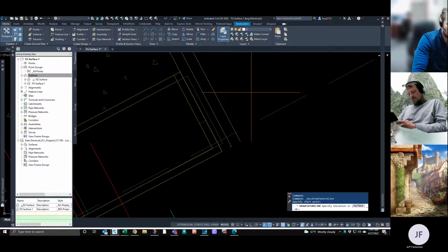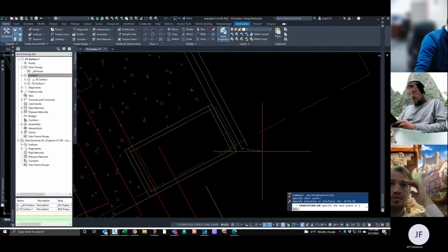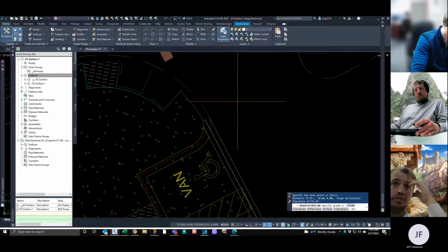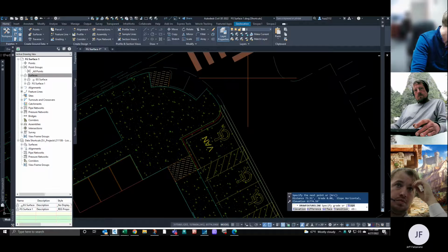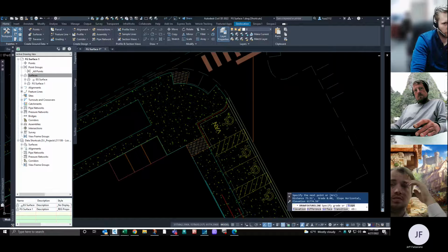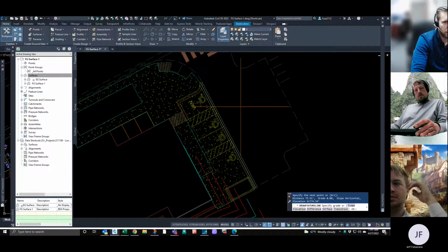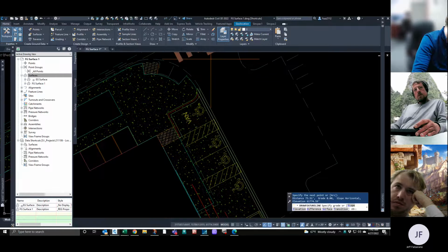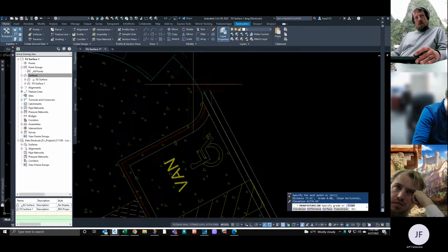And what was that elevation, Tyler? It was 6174.59. Once that elevation is in, then we go down to this edge here, and we have an elevation or a slope in between. The next elevation that I have is where the pan flow line meets the existing flow line, which is right there.